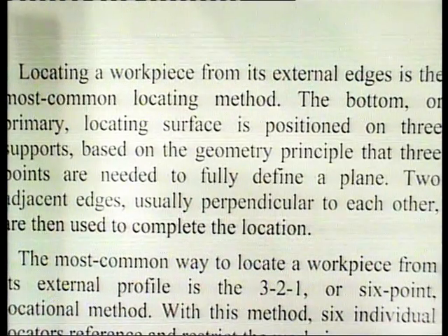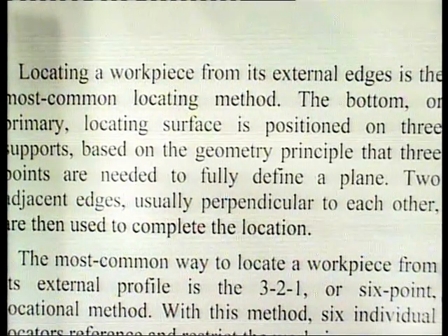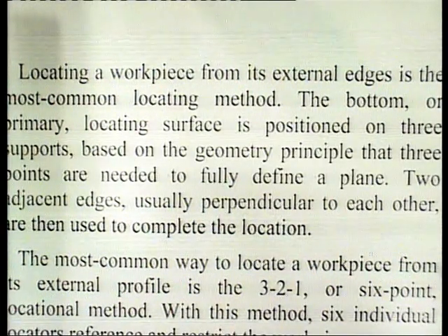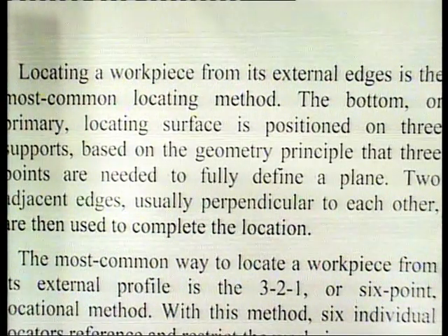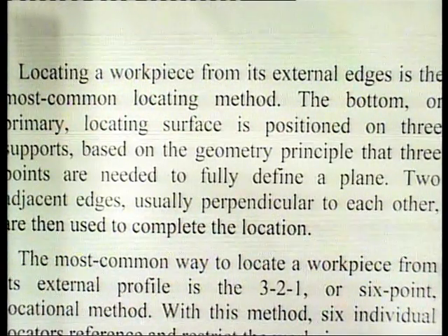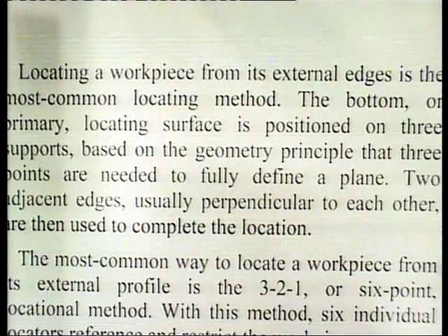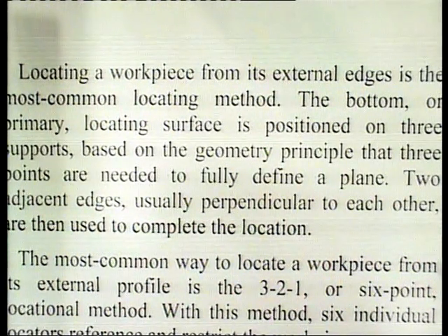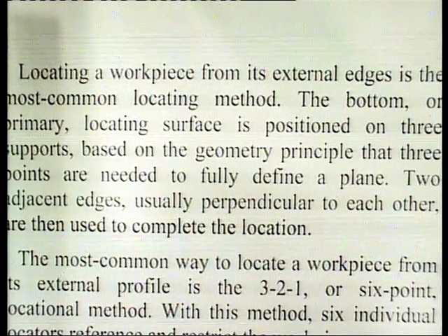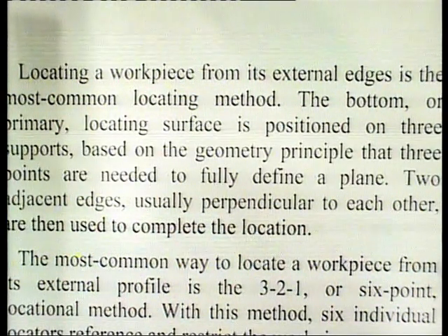The most common way to locate a workpiece from its external profile is the 3-2-1, or we can say the 6-point locational method. With this method, 6 individual locators reference and restrict the workpiece.